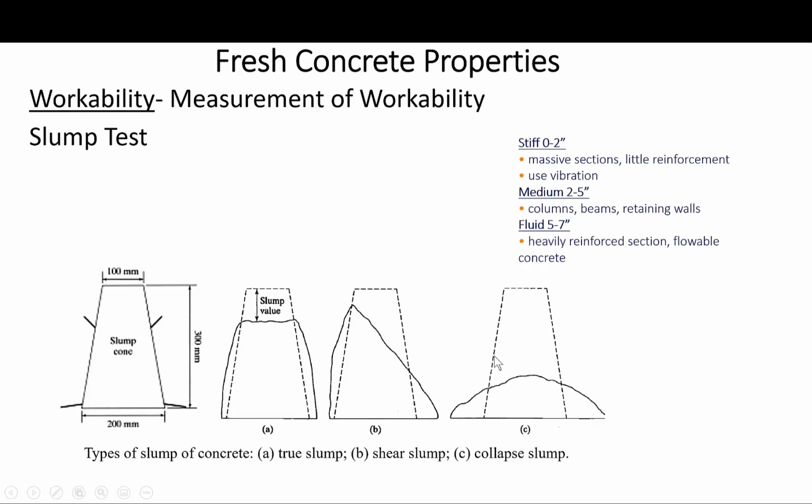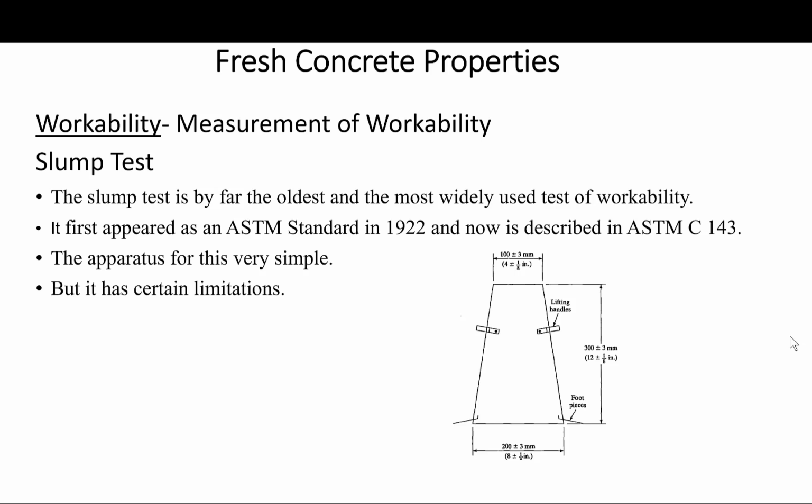What I mean by shearing off is something like this. If such shearing off occurs consistently, this indicates that this test is not suitable for this particular mix. We have to use another test to measure workability.